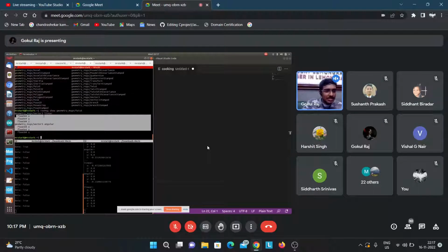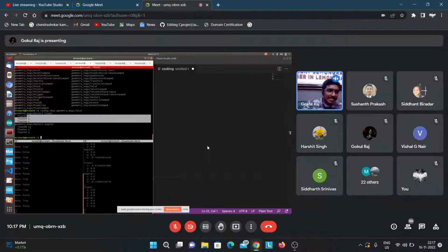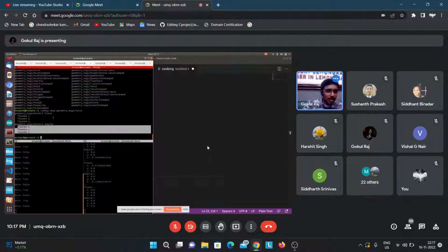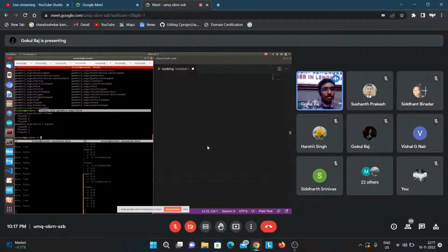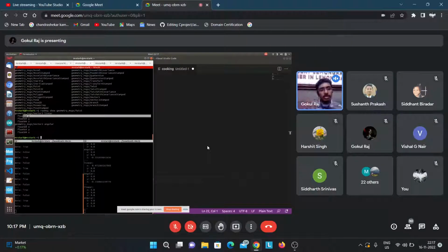My twist message has 2 different parts. One is linear, one is angular, and each of those parts has 3 subparts, XYZ and XYZ. This message is generally used for controlling robots. If it's a mobile robot, only linear X and angular Z will be needed. Linear X is for forward and backward motion, and angular Z is basically theta, how much the robot needs to rotate.